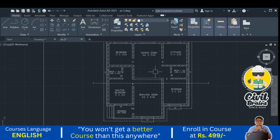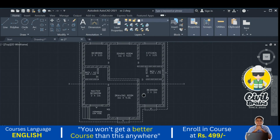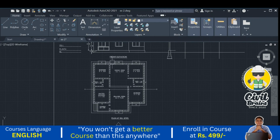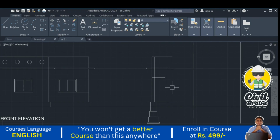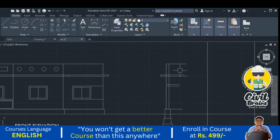Why do we need to keep the lintel over there? Because I am considering this is a load bearing structure. In a load bearing structure the lintel should be provided throughout the walls. Always remember, in a load bearing structure, wherever the walls are, whether partition walls or main walls, we need to provide the lintels. So that's why I am showing the lintels here. And above the lintels there is masonry, and above that the slab, then parapet work.